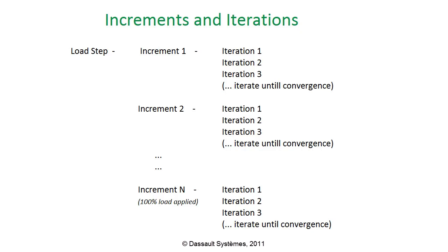However, in a nonlinear analysis, it is almost always better to set smaller increments. This is because the solver is unlikely to converge to the solution when it applies the entire load in one increment, and will internally do a cutback and try to solve with a smaller increment size. For highly nonlinear problems, Abaqus Standard might have to reduce the increment size repeatedly. This wastes computational time. Hence, it is preferable to have multiple increments from the beginning in any nonlinear problem.